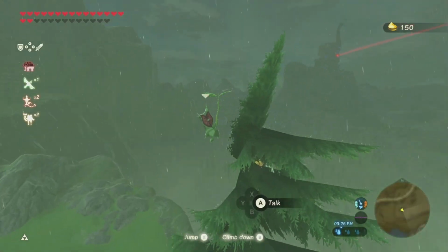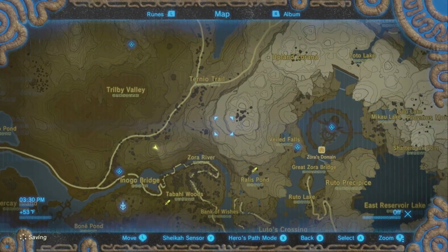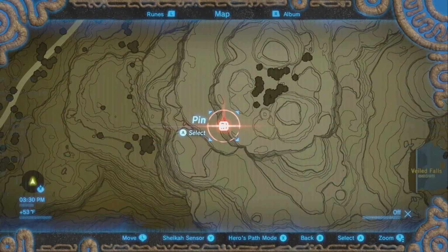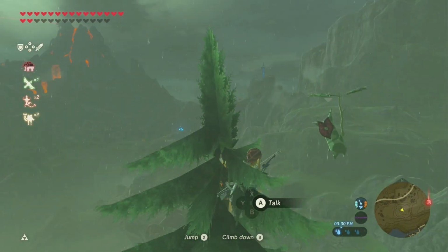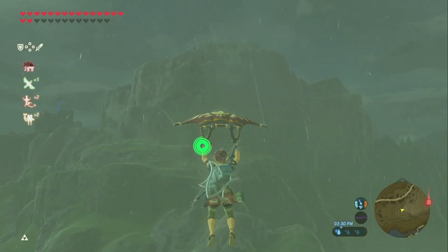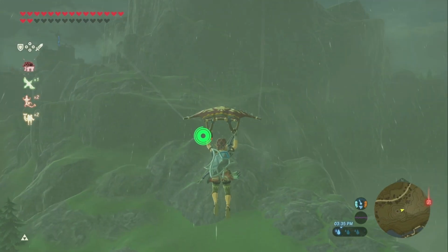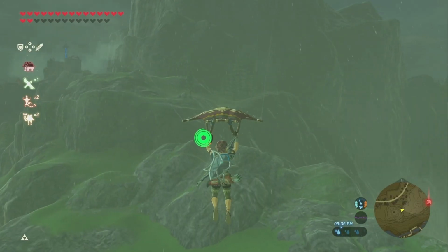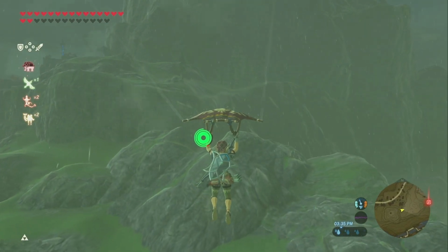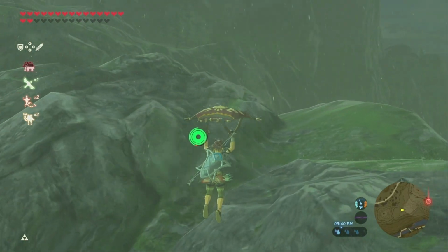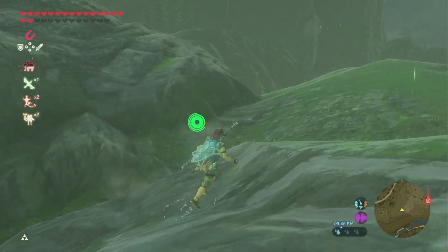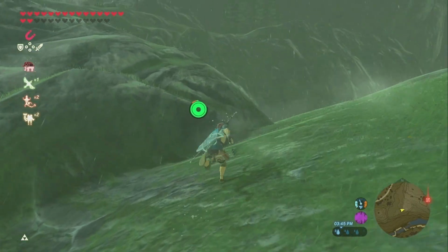Alright, next picture. Next example. Temperature rating for the pipe is 180 degrees Fahrenheit, 82 Celsius. And for this TPR it is 220 degrees Fahrenheit, 104 Celsius. This is not the proper pipe for this use. Next picture. Reduce line from the hot water discharge. Pipe size should stay constant.